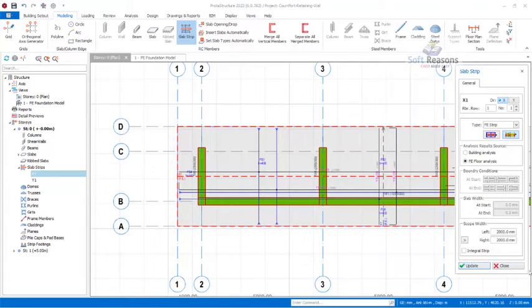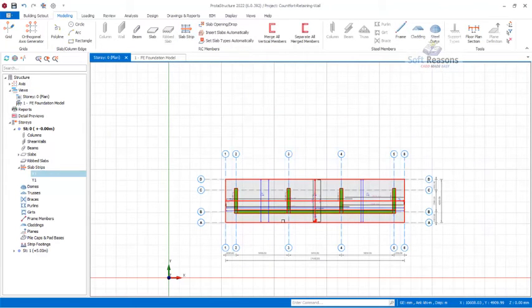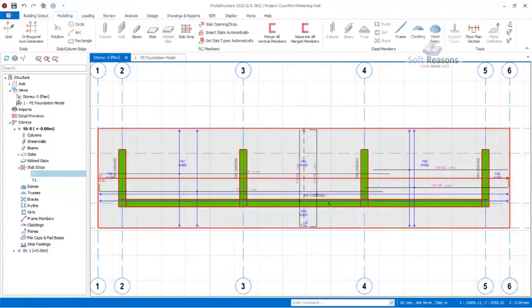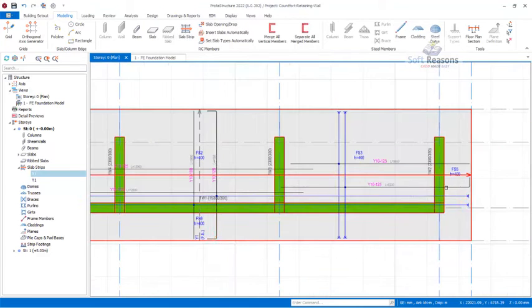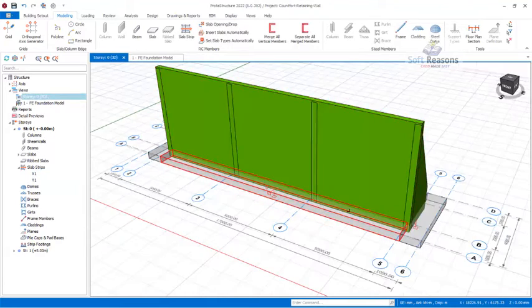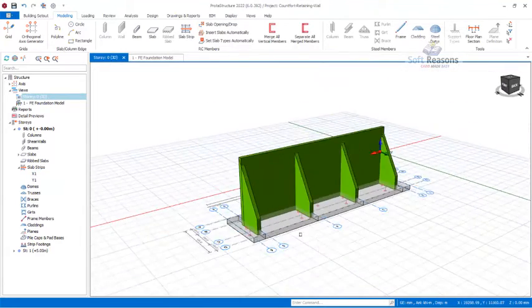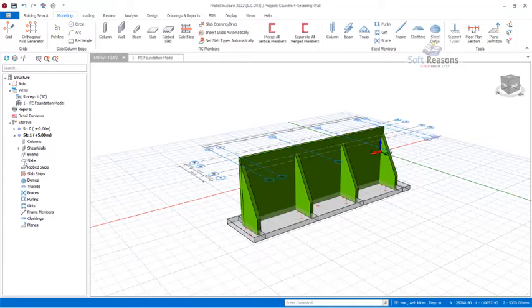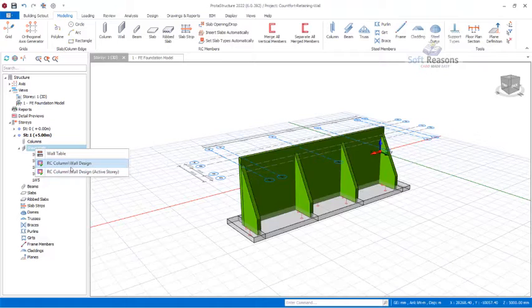All right, so we are done with designing the footing or the base of the wall successfully. We've generated reinforcement that will be used successfully. So after which we will navigate to the 3D right there. Having navigated to the 3D, we have to design the wall. For us to design the wall, navigate to story 1, then expand this wall. So we can click in this position, right click, and use any of these options, or you can design the wall 1 by 1. So we want to use these options.